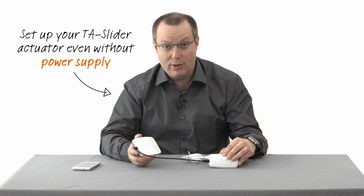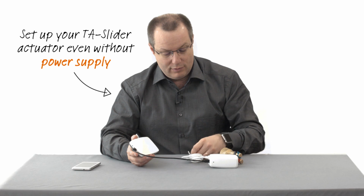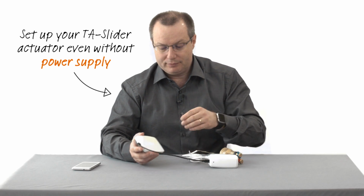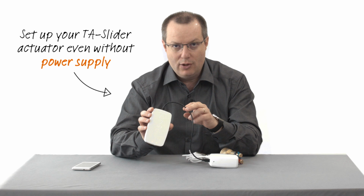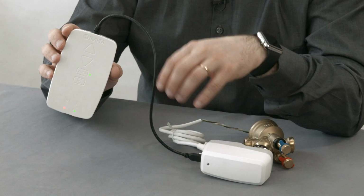One of the good features about having the TA-Dongle is that its battery is sized for powering up the TA slider 160 and TA slider 500, even though these actuators are not connected to the power supply. This means that by connecting the TA-Dongle to the actuator, you get an easy way to position it at a first position during commissioning time.